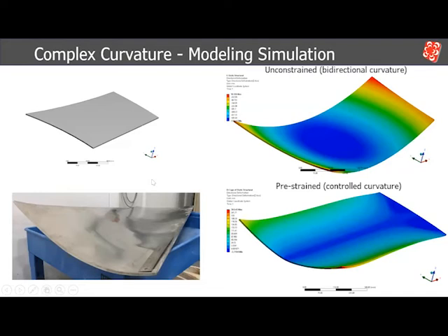So how do we go about some of this modeling and simulation work? We can add some constraints into our modeling. With the eigenstrain modeling, we don't really have the elastic constraints set up to handle the spring back issues. So this can create some variance between the laser peening simulation and the actual end product.